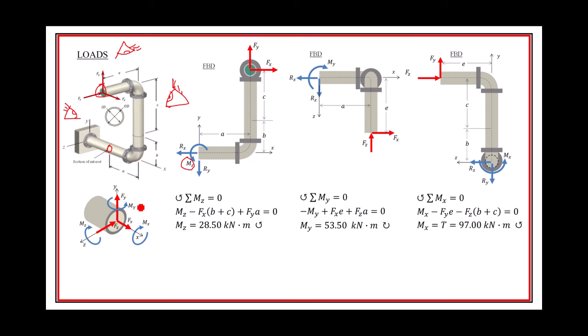Now, in this case, we're doing something differently than we've done in many other homework problems, and we're going to probably continue with this. We ignored transverse shear, and one of the reasons is now we don't just want to look at a particular element, we want to look at the worst case scenario, right? And the worst case scenario is going to be where there's the maximum bending moment, right? We're not looking at a specific spot. We have to find where that maximum is.